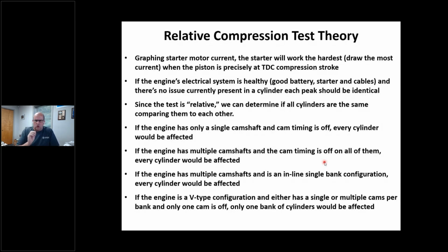If that camshaft is off, whether it's advanced, retarded, or whatever, all of those cylinders are going to be affected equally, okay? But when I have an engine with multiple camshafts, like a dual overhead cam, now I could have one cam off, and it should only affect one side potentially. Sometimes I can have an intake cam just slightly off, and I can actually have more compression than normal. The same thing with a bank-to-bank engine, a V6 or a V8: if one side's off, the other side is going to breathe a little bit differently typically, and sometimes you can see that in starter current. So that's kind of handy to know.